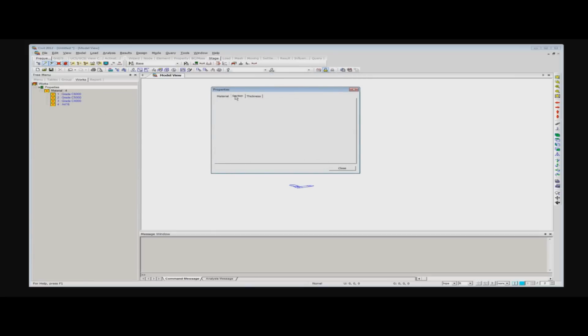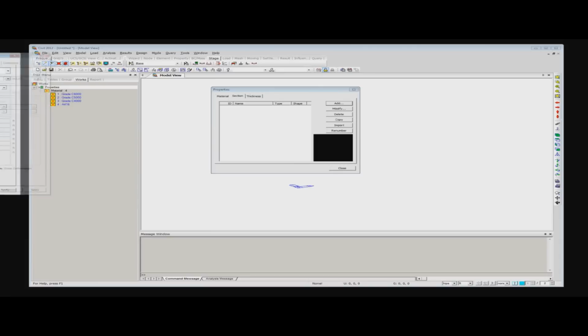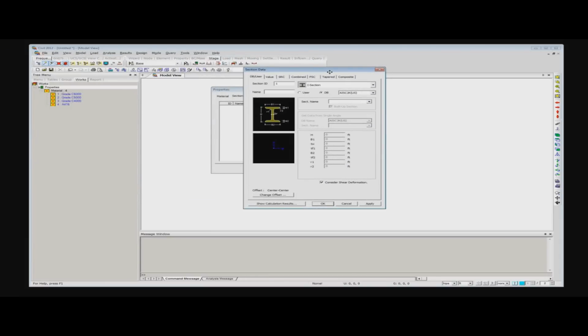Now I'm going to sections and defining my section. As I showed you, we have 2 sections. One is bulb tees, which is composite, and another one is box girder. So I'm going to model the bulb tee for you, and the bulb tee is actually composite. But the point is, here with the help of construction stages, we are modeling this structure in a way that software can calculate the before composite behavior and composite behavior. So the section property, everything will be changed.